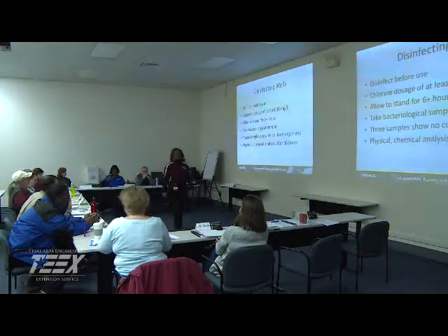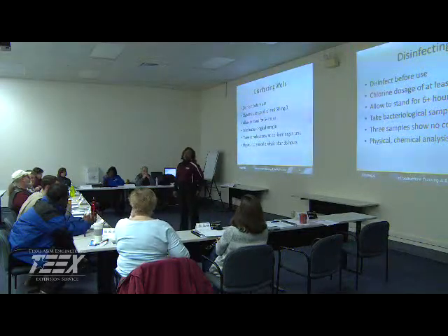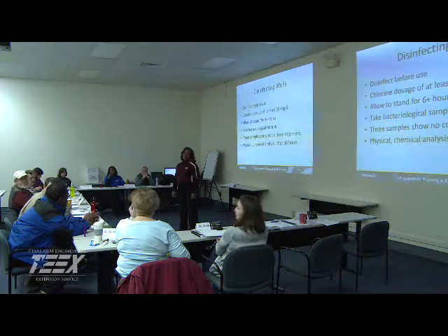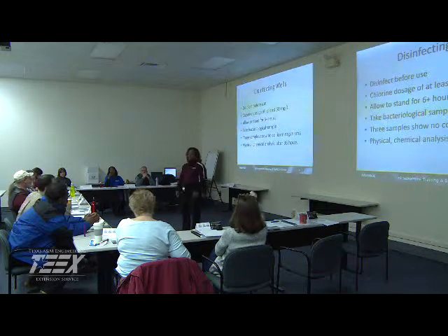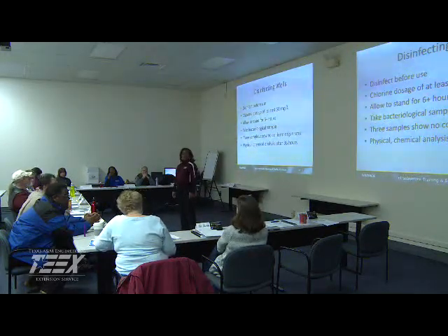Normally we let it sit for 24 hours. 24 hours, and that is one method. Do you all do 100 milligrams per liter for 24 hours? That's what, I think their recommendation is to dose it at 200. So 200? You should have 100 left after 20 minutes. Okay, residual. Got you. Our engineer came up with those numbers years ago.